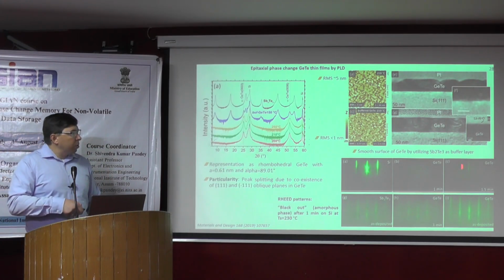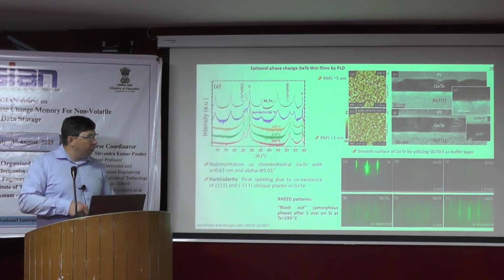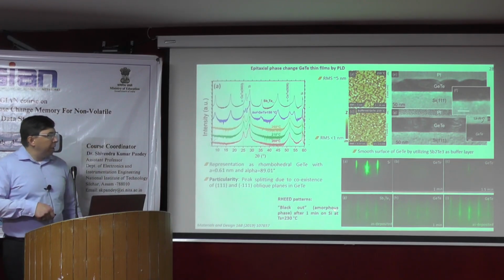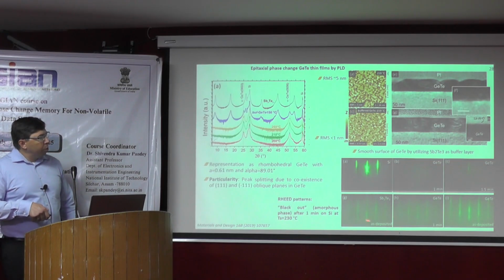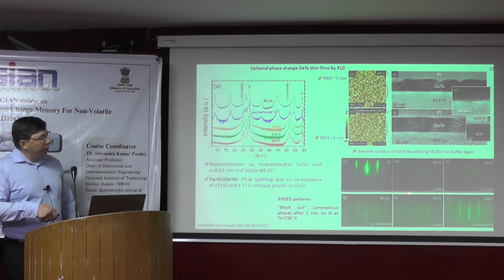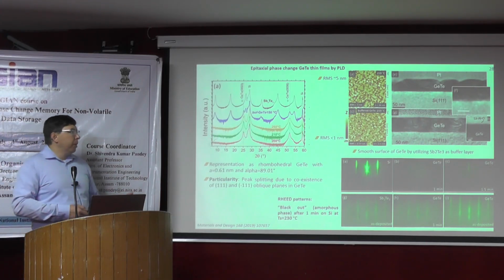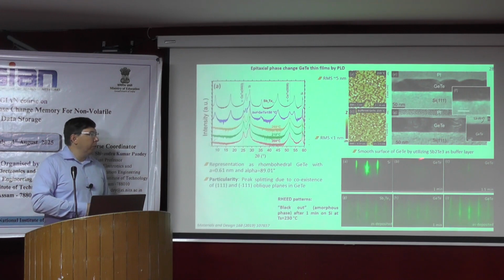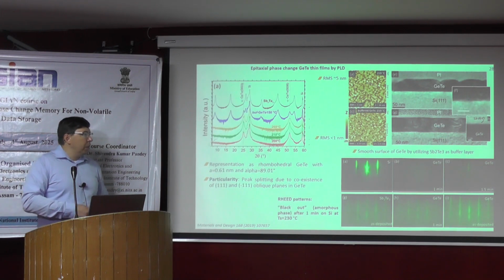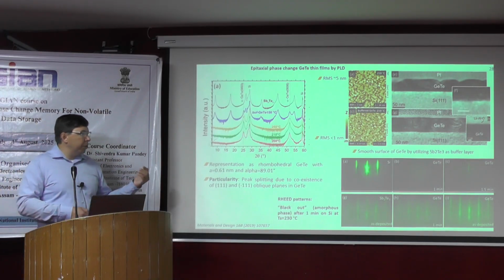So, it has also been observed not only by us, but also before in other papers. We don't have this blackout if you use antimony telluride as a seed layer. After 1 minute you see the really streaky pattern. So there is no blackout, there is a direct crystallization. And this is maybe due to the fact that germanium telluride grows differently as a trigonal phase change material.